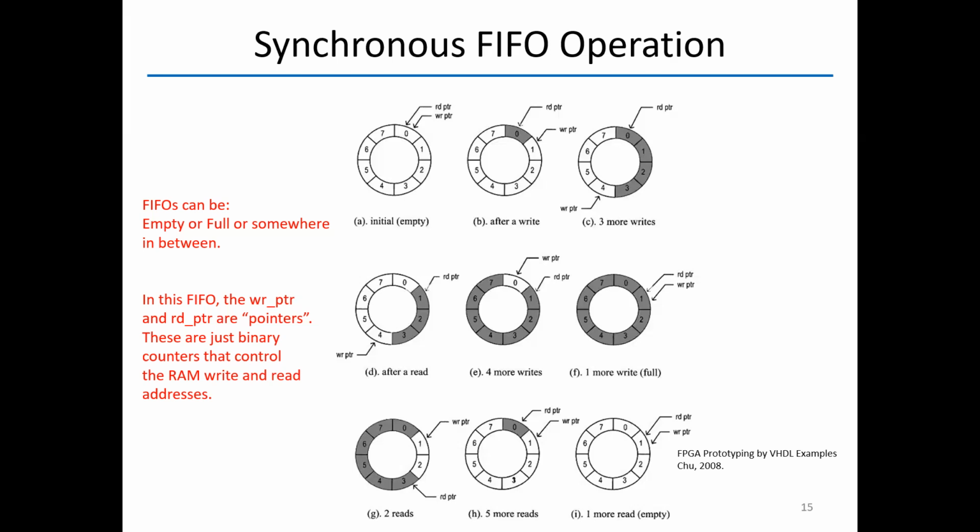And so the read and write just follow each other then, right? You have to finish writing first and start reading afterward. Oh, okay. So if you read more than the write, what will happen? There is no data to read, so you'll get a warning. It might be the data from previous runs. It can be anything, but it's not going to be what you are looking for. It is not going to be whatever is written by the write pointer.